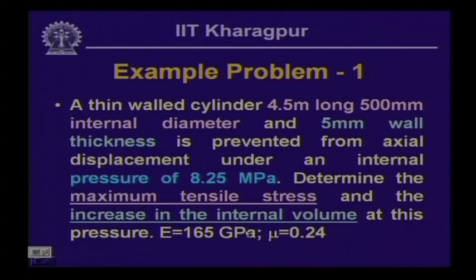We can find out the angle of rotation, the angle of twist because of this twisting moment, how much angular deformation that a bar undergoes. Now, in the previous cases we were evaluating, when the bar was subjected to axial pull, subjected to axial force, what is the stress, what is the deformation. Now, here we are computing the deformation and the stresses of the bar when it is subjected to a moment which is about the axis perpendicular to the cross section. Okay.